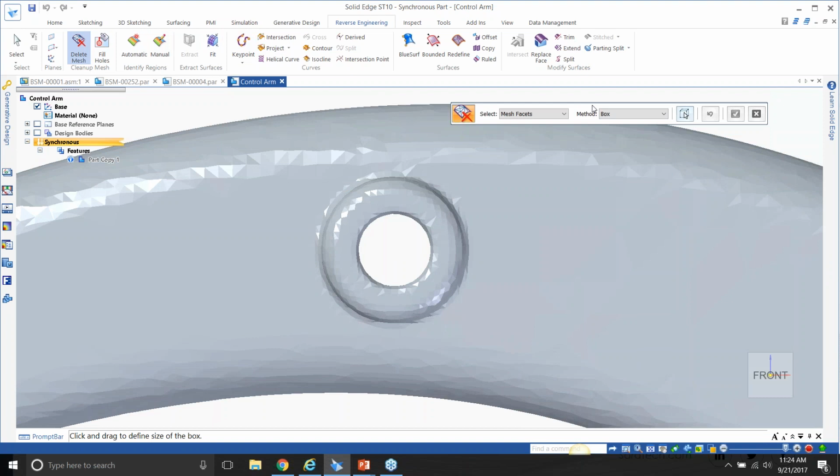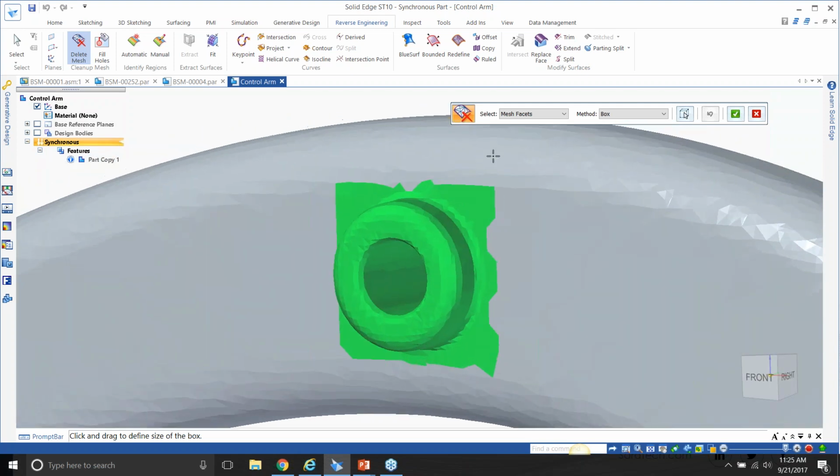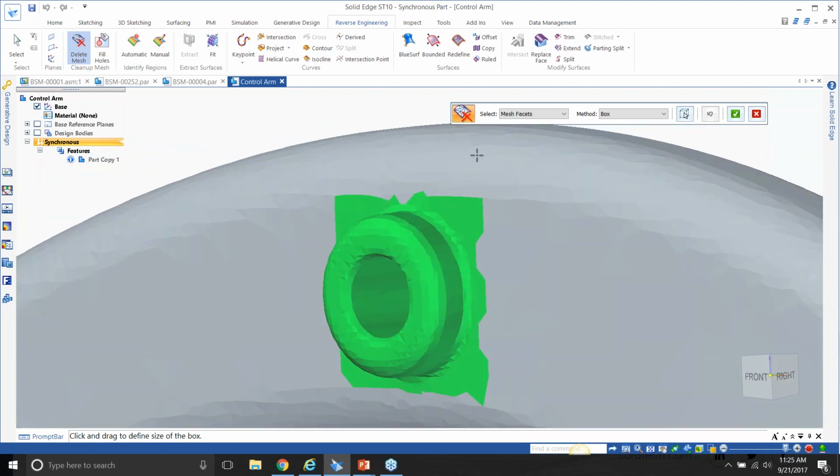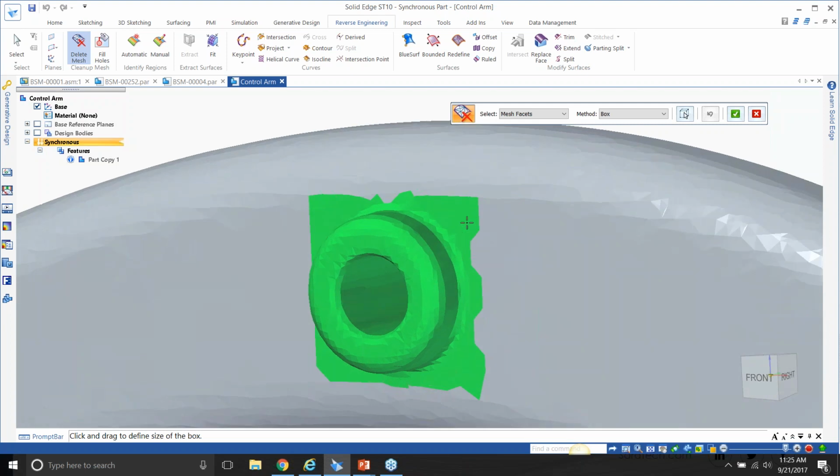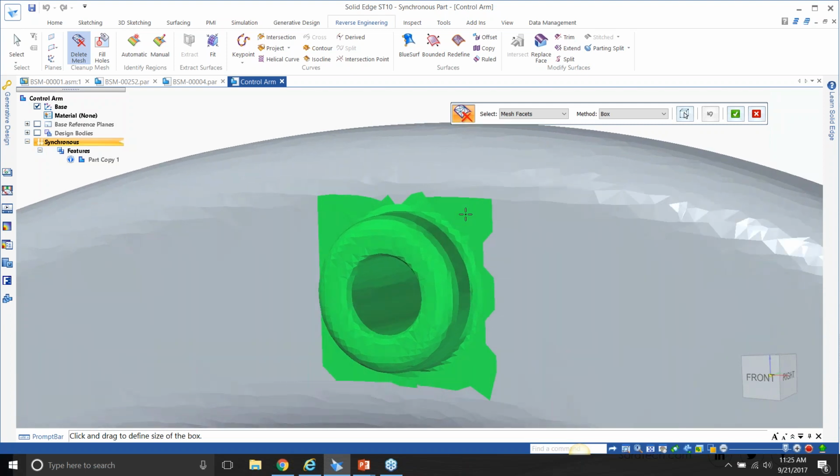But before we do this, I want to convey that you want to be very conservative with the mesh that you delete and keep, because you want to keep the original meshing. For the ones that are curved, you don't want to go between curved and linear, because it can get pretty confusing for Solid Edge to recreate and remesh the parts.